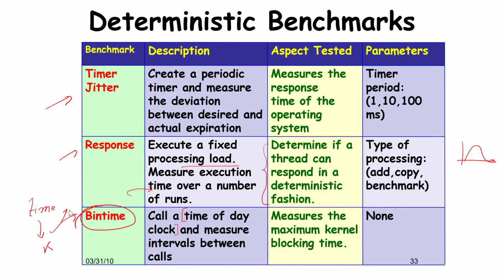So mind you, whenever you give a chance to the kernel is kind of opportunistic, right? So it will always take the chance to do some of its own work, execute some of its own code, which is not something to your liking, but this is something that the kernel will do, and this can cause a jitter.